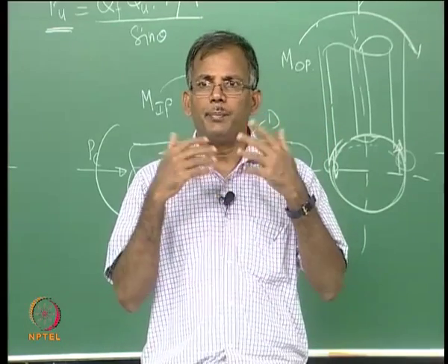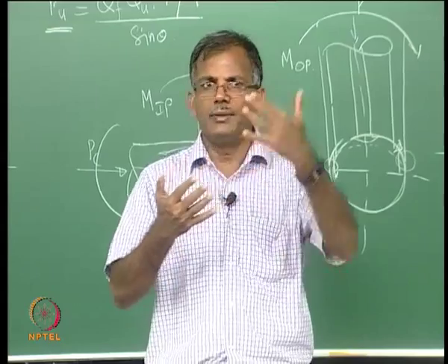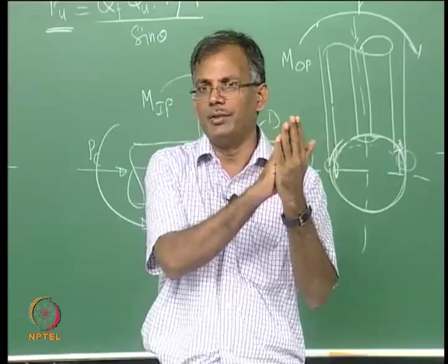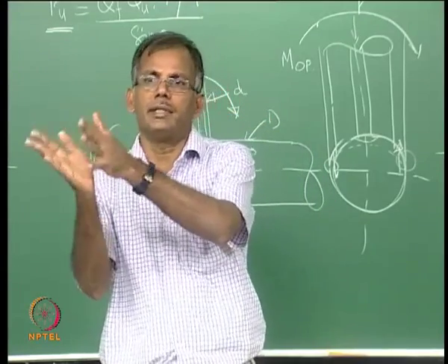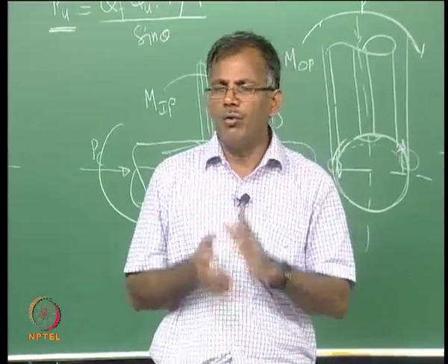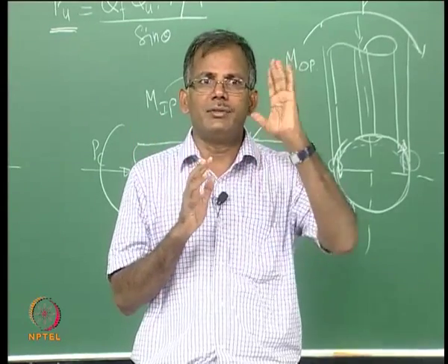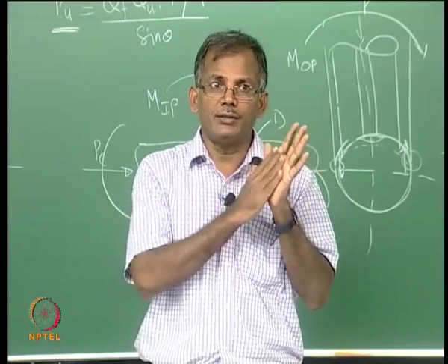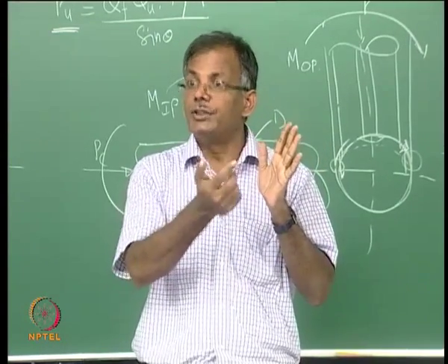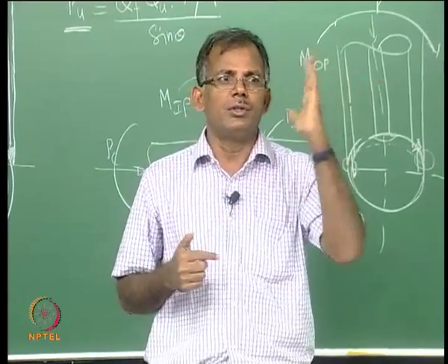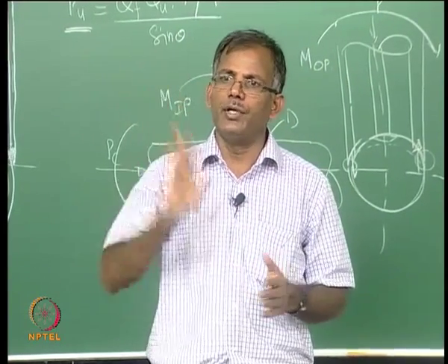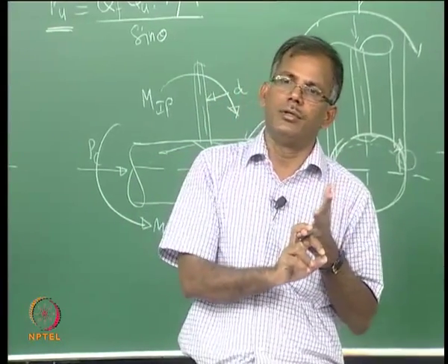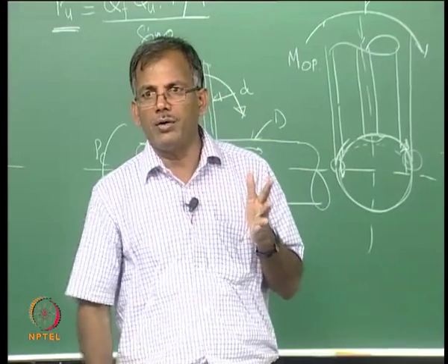Now, if you take a typical joint, you may get a combination of them, 50% K for one brace, 50% T or Y for the same brace, and the next brace could be 100% K, which is what we had. Now, how do we compute the capacity? Because we have classified a joint, which is just a few minutes of exercise, but after classification you calculate the capacities of each category. For example, you take only one K joint, one of the braces is fully K, the other brace is 50% K and 50% Y typically. So, how do we calculate the capacity of the joint?